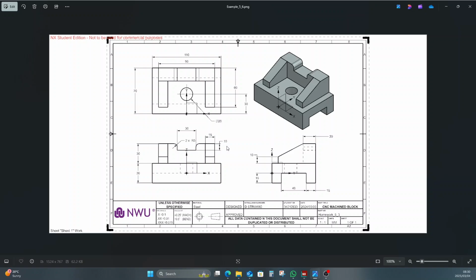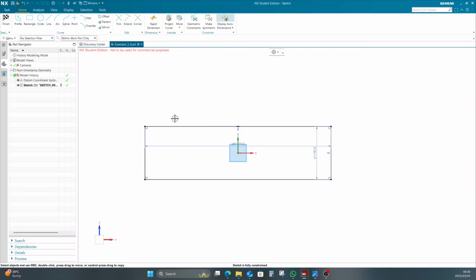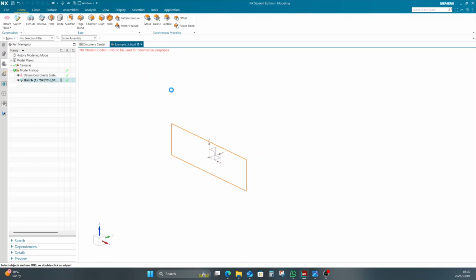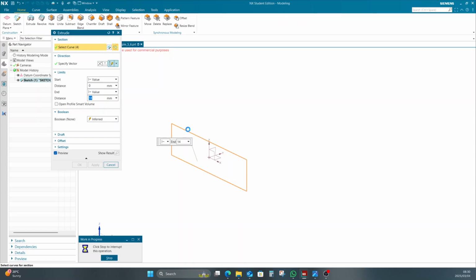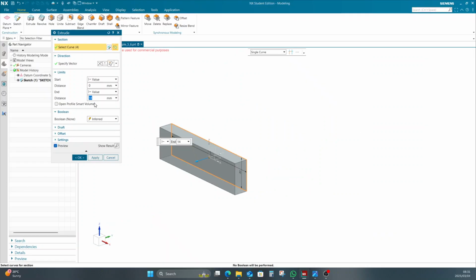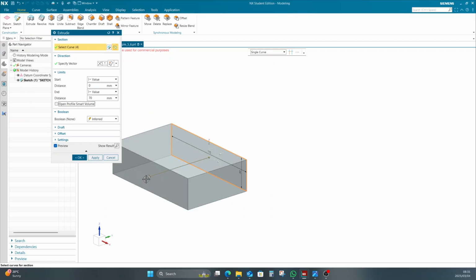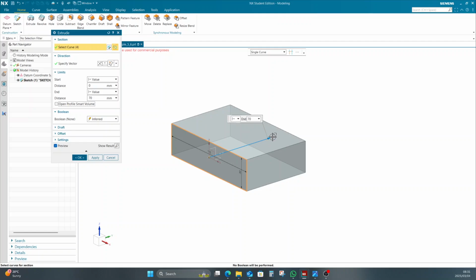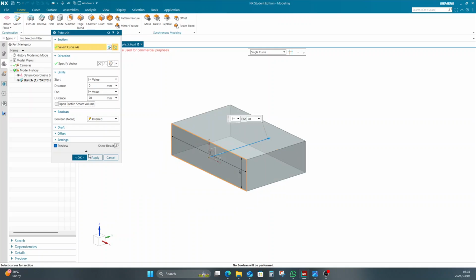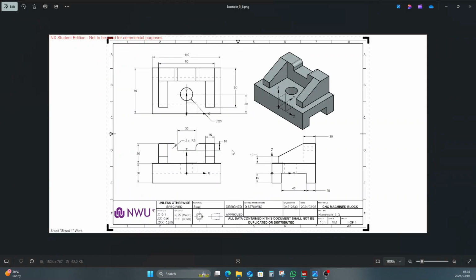So now it's quite easy. First I'm going to extrude it, so you can see it's 70 millimeters going into the y-axis. So I'm going to finish this sketch and use my extrude tool, and then I'm just going to extrude that curve 70 millimeters to the other side, because the datum coordinate system for my orientation needs to be on this side, so this extrude needs to go to the other side. Click OK. So we're done with that sketch.